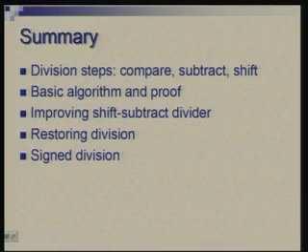So, let me summarize what we have done. We started with a simple hand worked example of 4-bit division in the unsigned case, and we noticed that using compare, shift and subtraction operations, you can carry out division in a sequential manner. Based on that we developed the basic algorithm, analyzed it thoroughly to ensure that it is correct, and from there we derived the circuit.